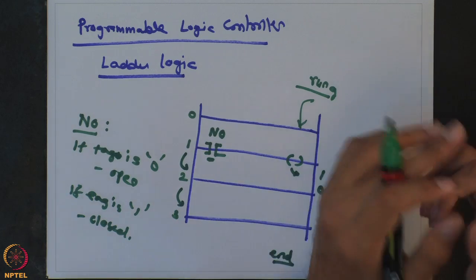There may be some 1000 or 2000 rungs inside a programmable logic controller. So, during every execution of a PLC, it will go through all these steps and then come back. And just for your information, typically the cycle time is about some milliseconds. So, you can see that these actions take place very fast. The cycle frequency of these PLC controllers is of the order of milliseconds. And mind you, there are generally thousands of rungs within a single PLC.